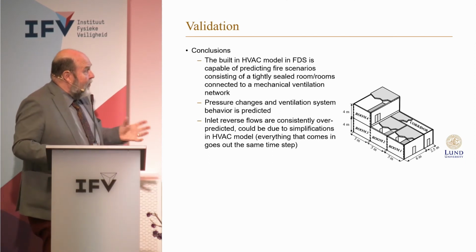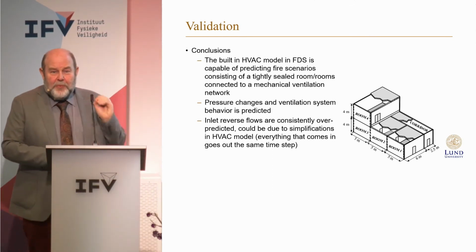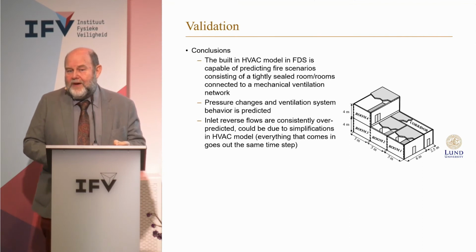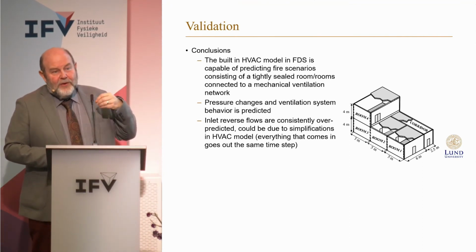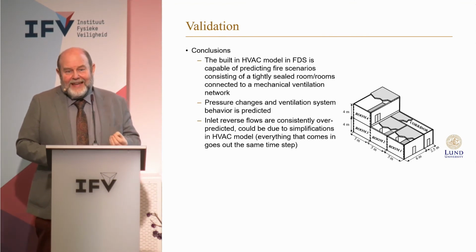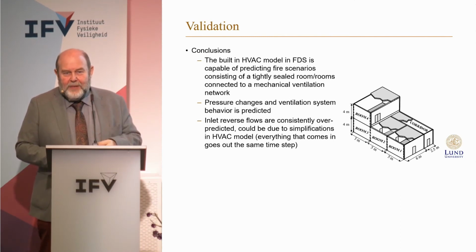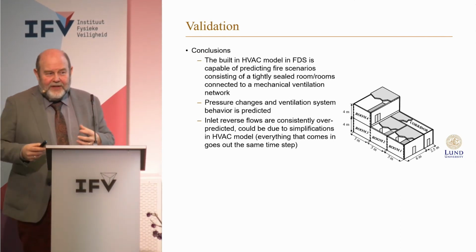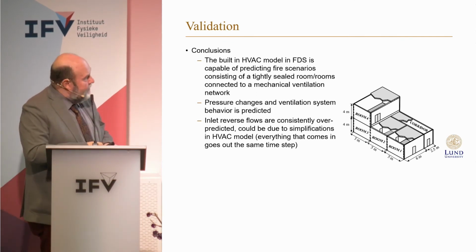The inlet reverse flows are predicted, so you could detect, okay, there's a problem here with this scenario, with this type of fire, I get backflow. You also got a very good indication in the model if you got into either a real underventilated condition or even into a kind of oscillating behavior where you get this back and forward, which is very tricky in case you would start opening these rooms.